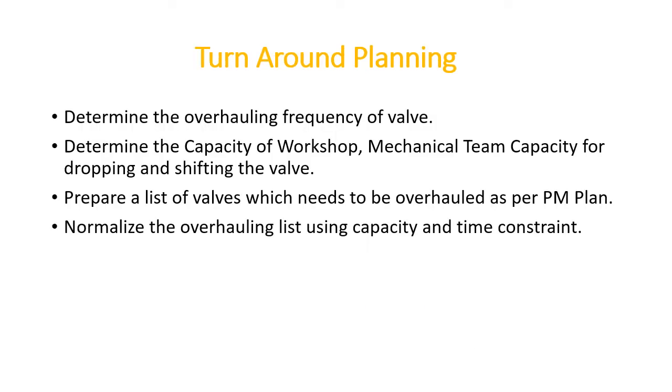Another thing is turnaround planning, which is very important, and you need to define what the overhauling frequency of the valve should be. For the critical valves, you can plan overhauling every 4 years or every 8 years, and for non-critical valves you can plan the overhauling every 12 years.